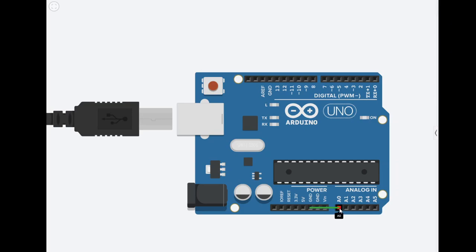So what I've done is I'm using A0 as an analog input. Now A0 corresponds to ADC 0 in the Atmega 328. And what I'll do is connect this wire here to either the ground, 5 volts, or 3.3 volts. And then we have three analog values, and let's see what we get as an input.